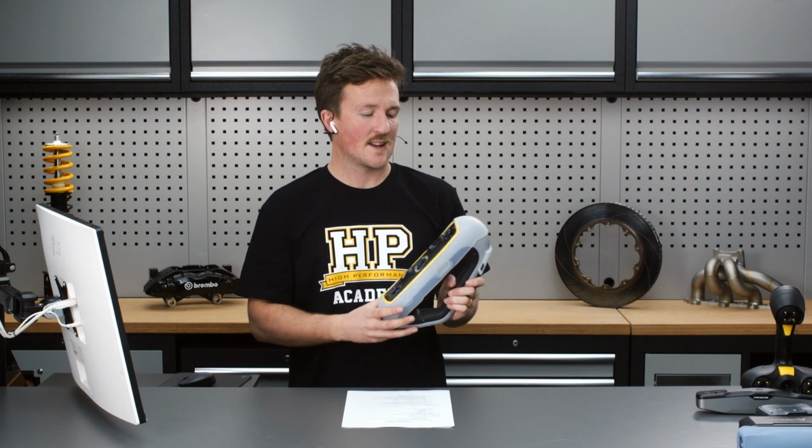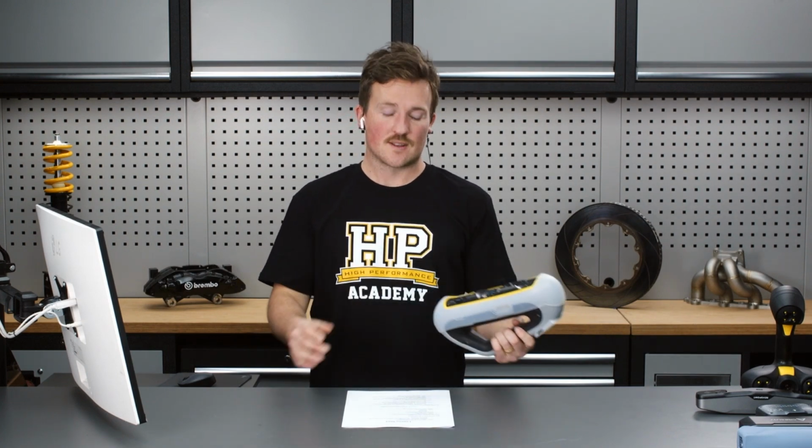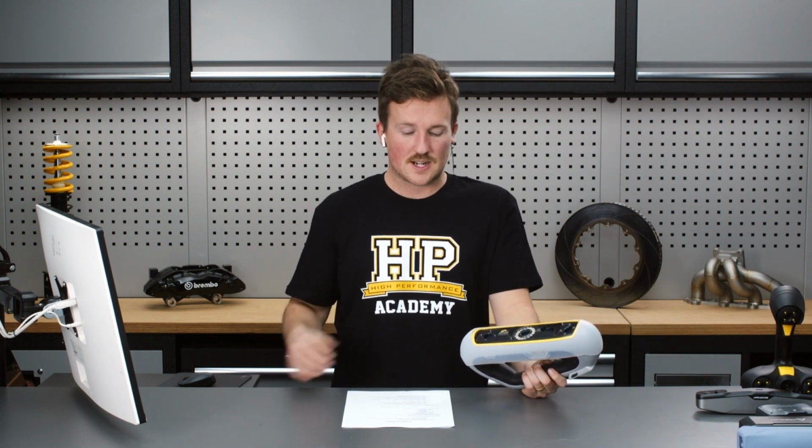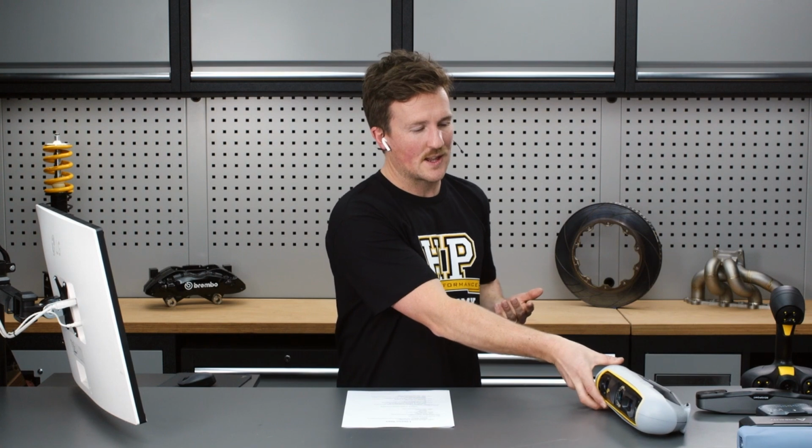Within the structured light realm of these 3D scanners, there are a lot of different variations, and that's typically around what the light source is. Generally the most common one, or previously the most common one, would be white light 3D scanning, and then there's also blue light and infrared. If you studied physics at school with light waves and things like that, then you'll maybe understand that's the difference between structured light and laser scanning as well. The intensity and also the wavelength of that light is the key difference there.